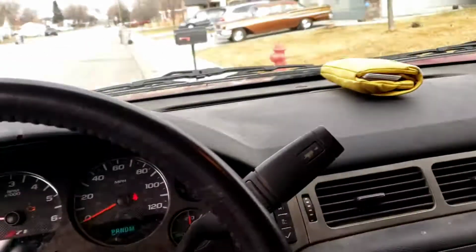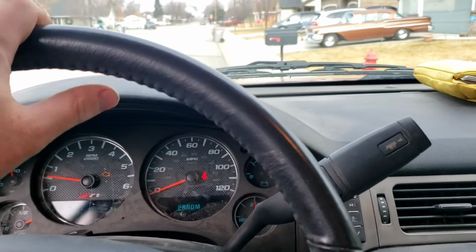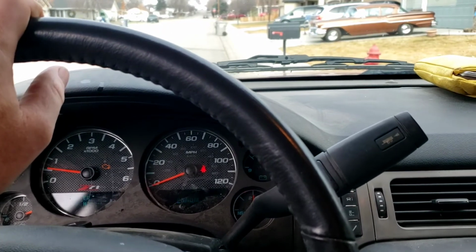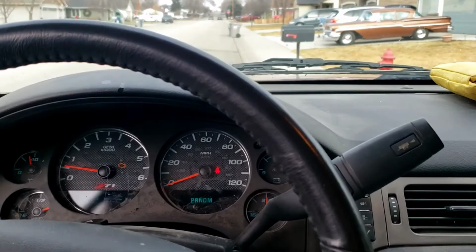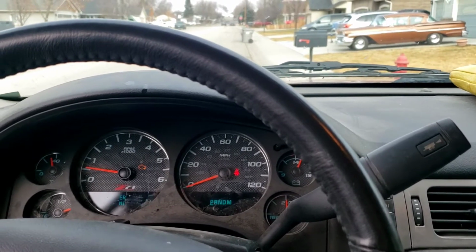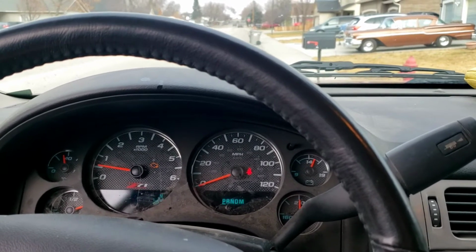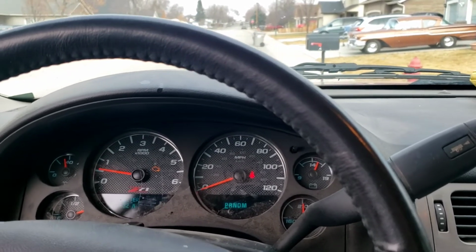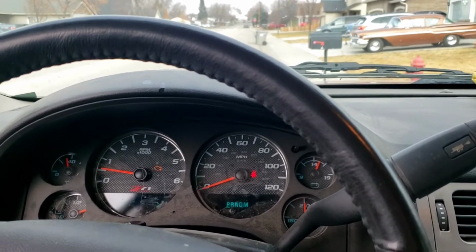So on the engine, they have a purge valve on the engine. And in the gas tank, they have a fuel tank pressure sensor that reads pressure and vacuum. And also back there in the fuel tank, they have a vent solenoid. So what they do to test the integrity of the system for leaks is, when the engine's running, it'll close the vent, because the vent in the back of the fuel tank is normally open. So obviously your vapors can vent out through a charcoal canister and not hurt the atmosphere. If it wasn't normally open, you'd have fuel vapors in your garage, wherever you parked. But when it's running, it's doing a self-test.